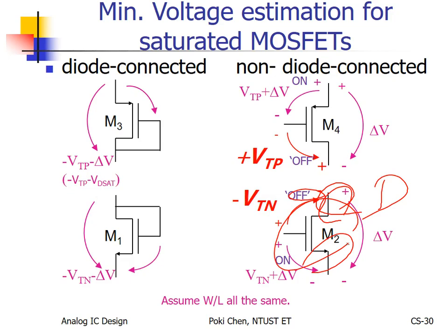In this way, we can get more of the so-called output swing. Output swing will be larger for the drain. It can be lower, and how about how much higher? In theory, there is no limit. But in practice, it goes until the drain gets into breakdown region, usually more than 10 volts for mature processes. For new processes, I think a few volts at least.